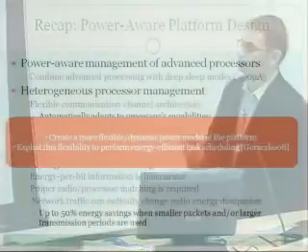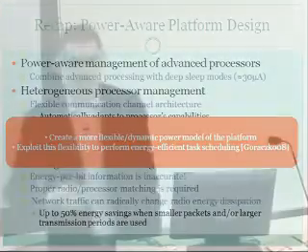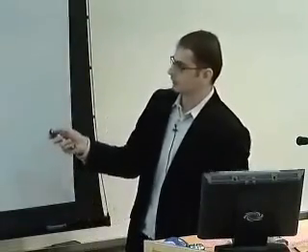And then I quantified some of the trade-offs at the hardware level and at the network level with respect to the energy efficiency of the radio. The whole goal of what I just described is to create a very detailed power model that can be exposed to the software and scheduling techniques so that we can take advantage of the lower level power control to create more energy efficient application scheduling on the platform. And there is one work that has been trying to use part of our results to do that. It's going to appear in the Design Automation Conference this summer.